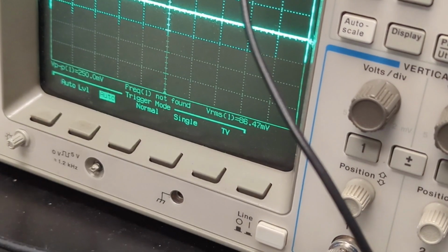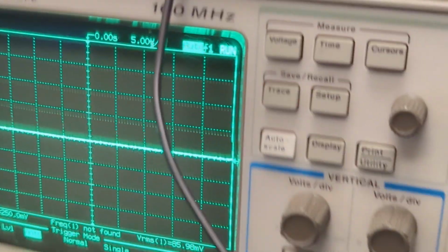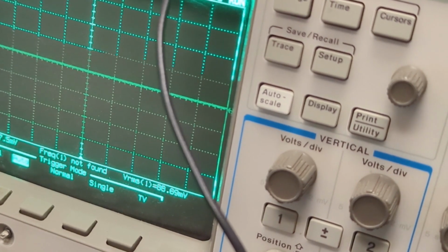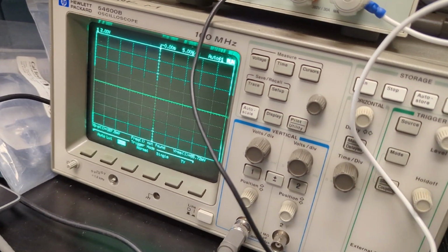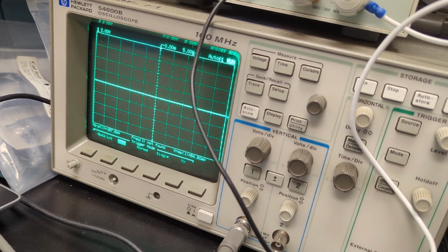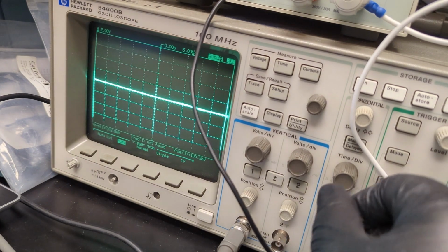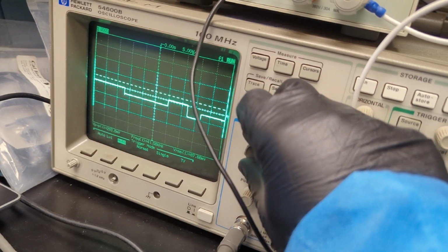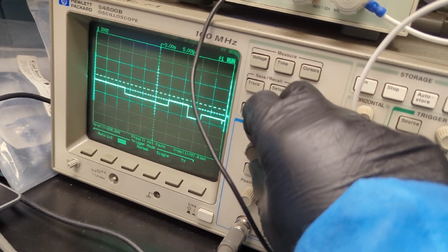And there should be nothing coming from a no connection pin. That's usually an indication that there could be something wrong with the chip. I mean, that's usually what I take that for when I see things like that. And I'll show you that right now. Let's find U435 again. It doesn't look like much, right? But let's zoom. There you go. So look at that.